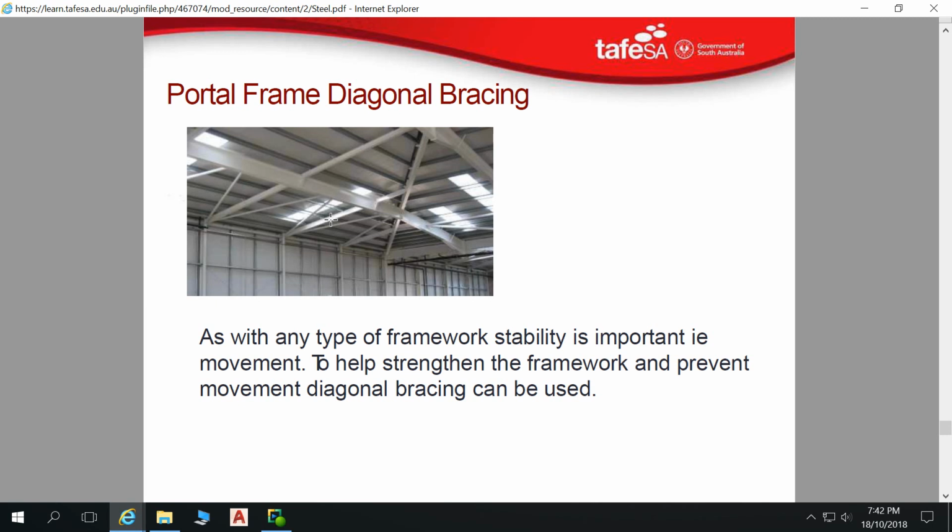You've got to get it slightly too short, and then screw your bolts in that pull it up nice and tight. Of course, they didn't do that, and so you've got bracing which sags. It does nothing. So in a high wind event, the fire station there is going to buckle until that bracing becomes activated. So it's got to move a fair bit until the bracing becomes tight. You understand that? Yeah, straight away.